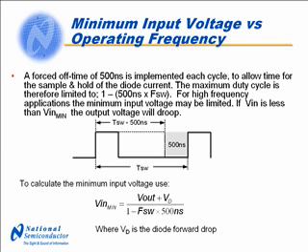Ideally, for a buck regulator, the output voltage will remain in regulation even when the input voltage is reduced to almost equal to the output voltage. The maximum duty cycle limit requires the input voltage to be higher than the output voltage. The minimum input voltage predicted in the above equation is the lowest input voltage where the output voltage can still remain within regulation.